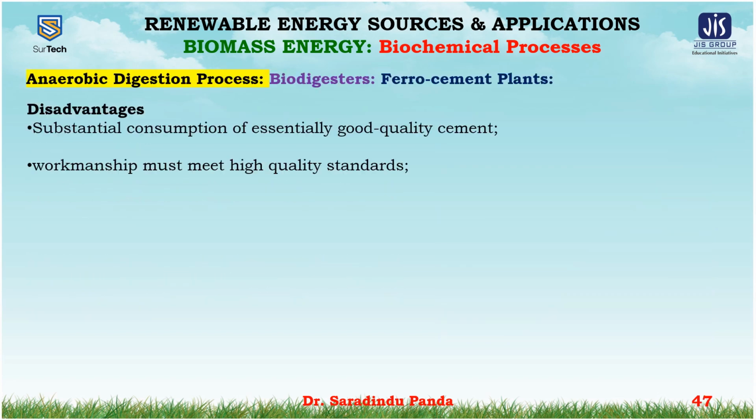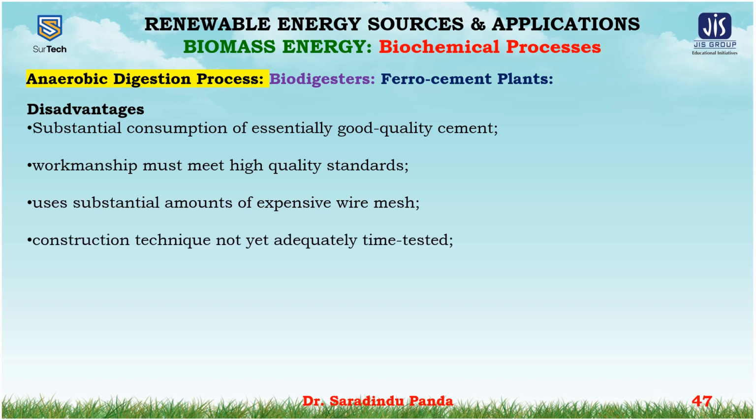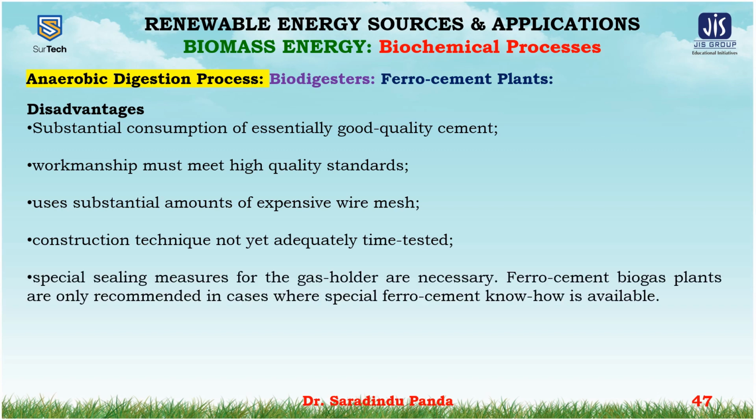Some disadvantages of ferrocement plants: the substantial consumption of essentially good quality cement. Workmanship must meet high quality standards. It uses substantial amounts of expensive wire mesh. The construction technique is not yet adequately time tested. Special sealing measures for the gas holder are necessary. Ferrocement biogas plants are only recommended in cases where the special ferrocement know-how is available.